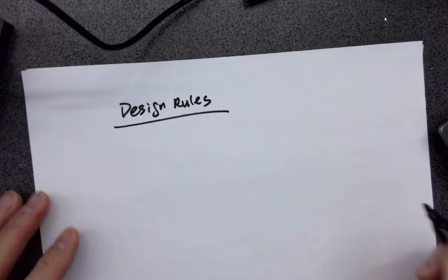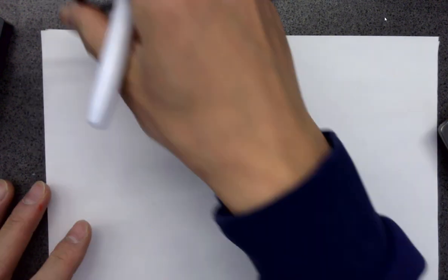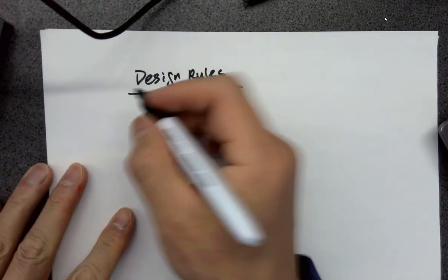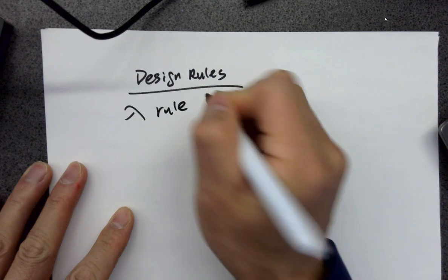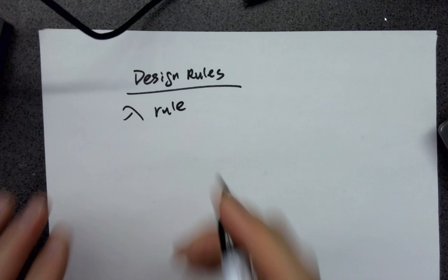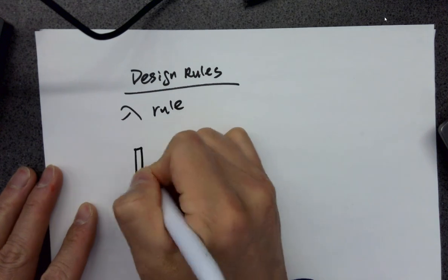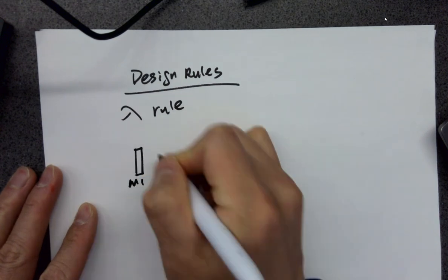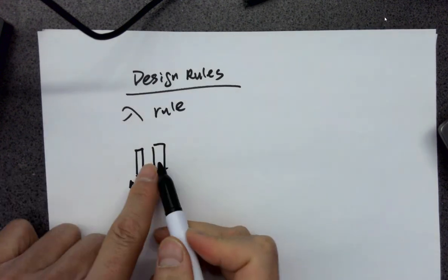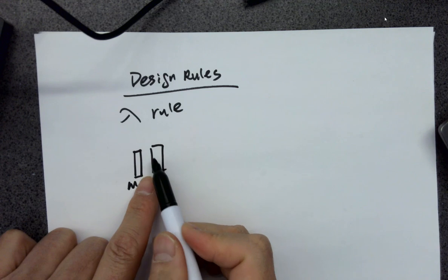We don't need to memorize any of the rules because eventually, even for Electric VLSI as a free software, it has the lambda rule embedded inside the software. So eventually when you are placing the metal, like metal 1 and metal 1, you are placing them too close to each other, and there will be an error showing in the window.